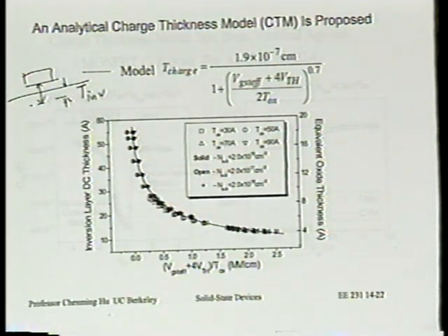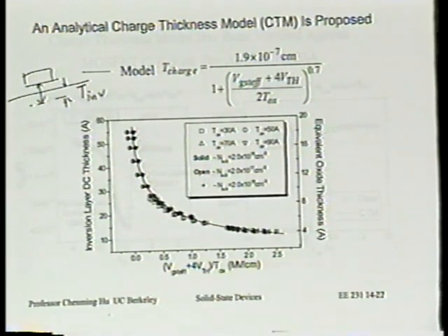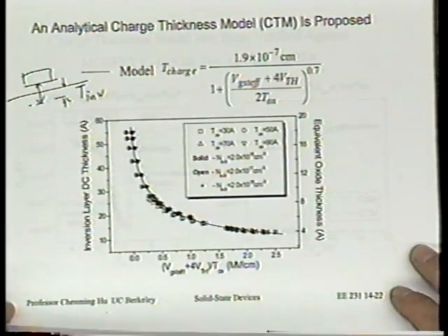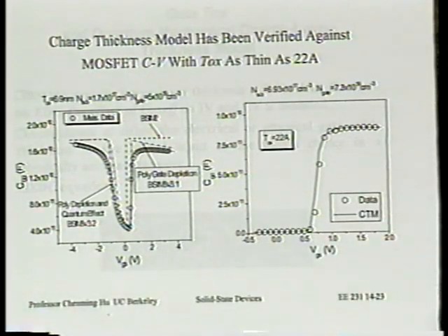And what makes this really interesting is that this is saying the effective dielectric thickness is not a constant, but a strong function, maybe not so strong, a function of Vg. Why? Because this inversion layer thickness, or centroid, is a function of Vg plus Vth. Remember that? Following what I'm saying? All right? This is a VGST effective, okay? Plus a Vg. Remember? So this also is put into BSIM 3 first for the CV, and also in BSIM 4 for the IV, okay?